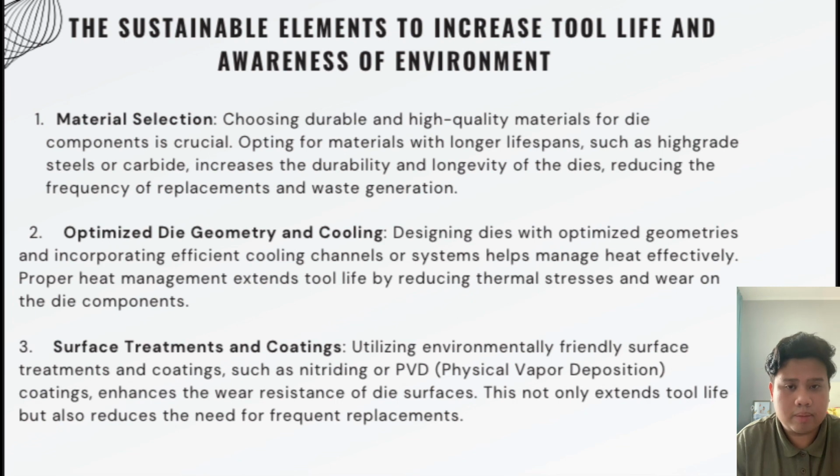The next is sustainable elements to increase tool life and awareness of the environment. First is material selection. Choosing durable and high quality material for die components is crucial. Opting for materials with longer lifespan, such as high-grade steel or carbide, increases the durability and longevity of the dies, reducing the frequency of replacement and waste generation.